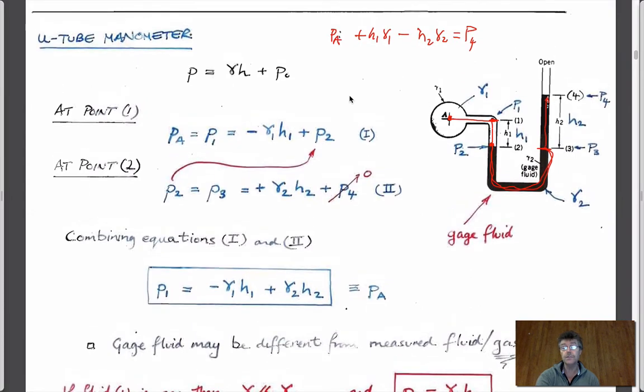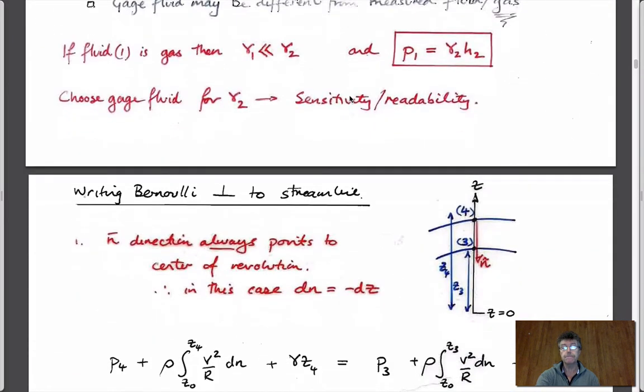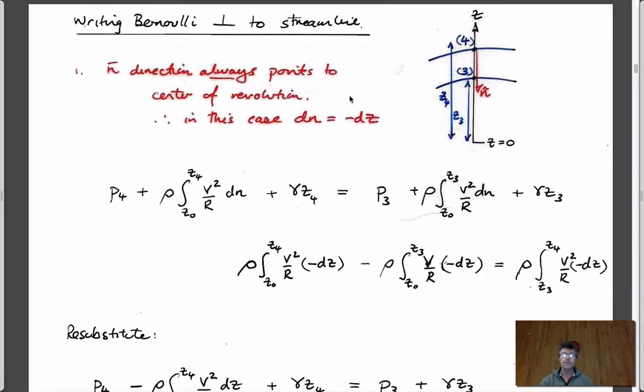So manometer equations: if you go down in a fluid, pressures go up, add pressures. If you go up in a fluid, pressures go down. If you go up in a gas, the density of the fluid is very small compared to that of a liquid, and therefore you don't care. If it's evacuated, it's the vapor pressure, and so those are all worth knowing. Okay, but they do come out of Bernoulli, even though you perhaps don't think of them that way.